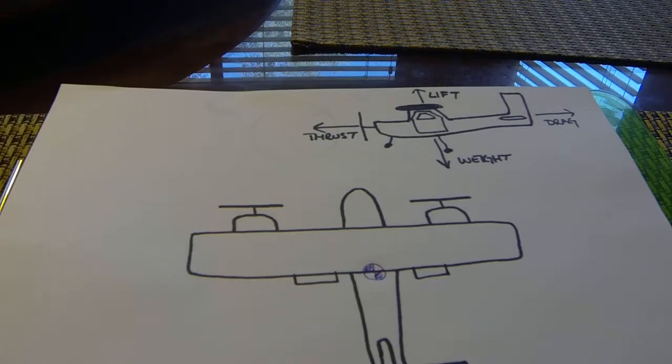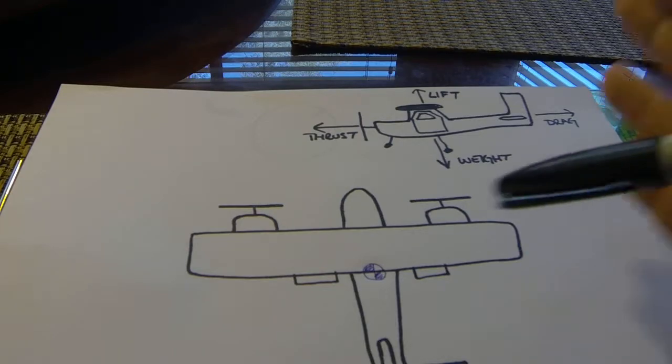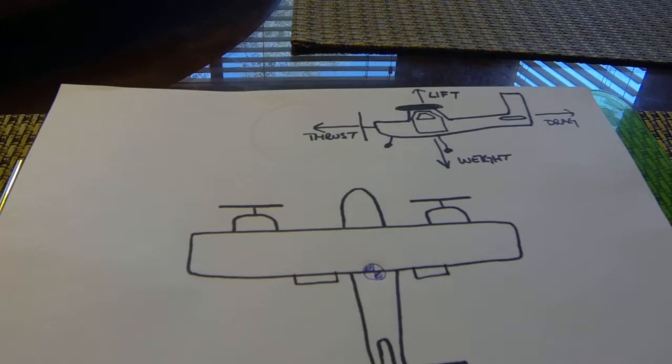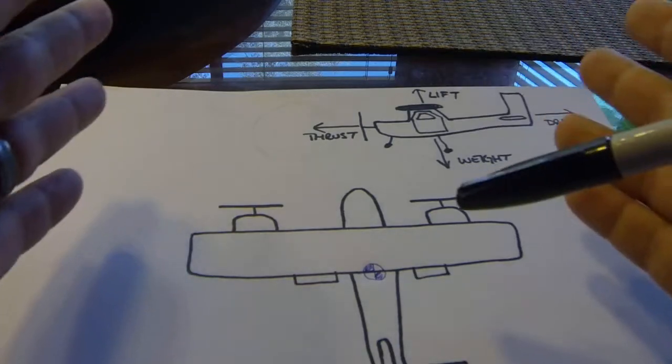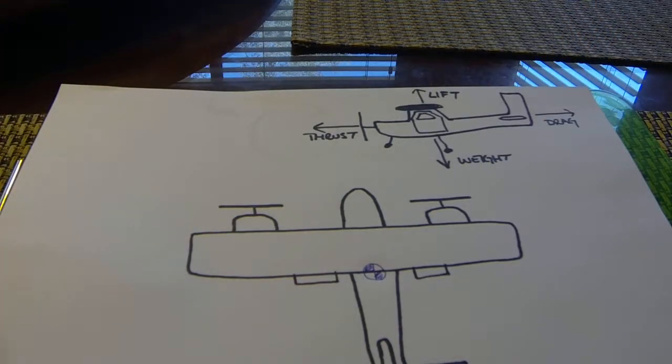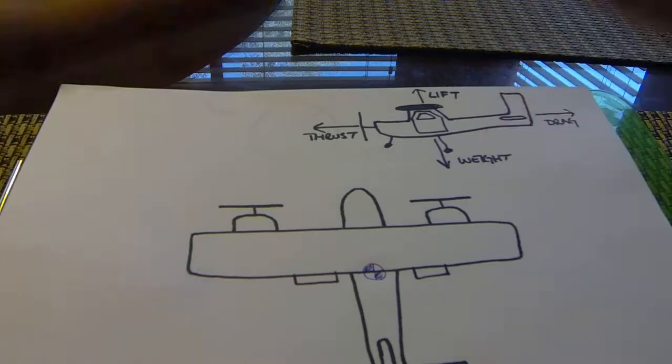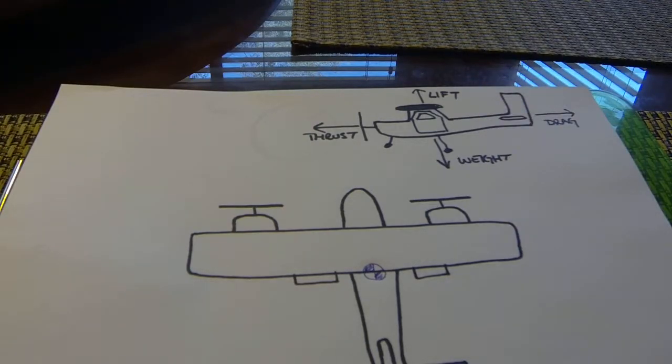Why retracted? Well, the landing gear provides some stabilizing effect, kind of like a keel on a boat. We've got the landing gear, we've got the doors. It may provide some directional control, so we want to get rid of that and just use a clean aircraft.